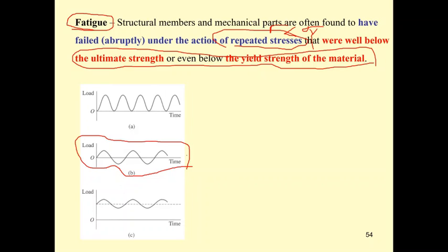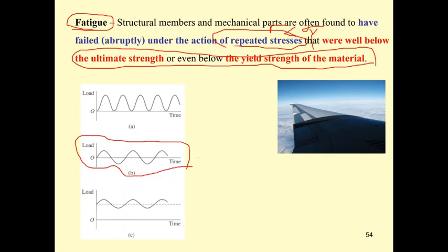If you cannot feel this, you may cut your finger with a small wound, and then push it up and down, up and down. You will feel that when you pull it open, it hurts a lot. The same thing occurs in steel, and when the crack gets bigger and bigger, there is less material to resist the force, and then it fails directly.